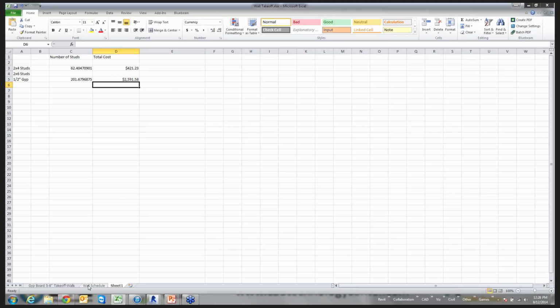You put it all into a singular spreadsheet, and now I can distribute this information to my purchasers and a handful of other individuals within the project, and they'll be able to go ahead and insert that into whatever type of database that they need. And because it's an Excel format, they have the ability to just literally take this sheet and bring it right in. And depending on what formats they need and what different calculations that they're using, we can utilize their sheets and their information in this fashion, and just kind of link their sheet up to the exports that we're getting out of Revit using Spreadsheet Link to go ahead and put all this together.